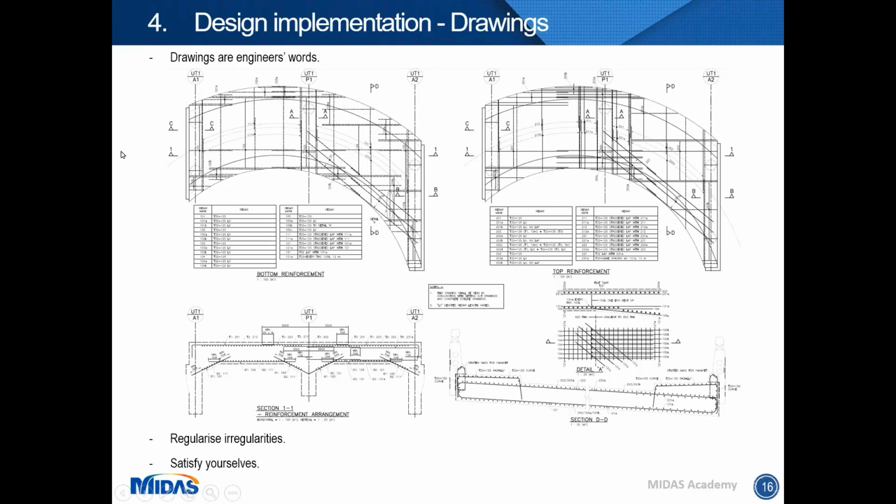So here is the longitudinal section of the bridge with the scales different horizontally and vertically. What I want to show actually is the reinforcement here at the end of the tapering area. A larger view is here. The bottom reinforcement of the tapering is clashing with the horizontal reinforcement from midspan.